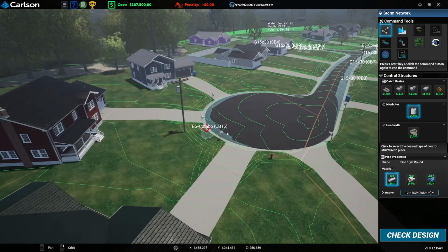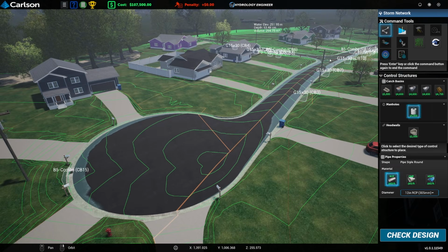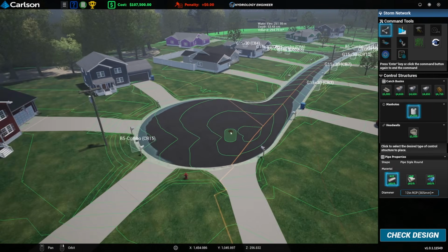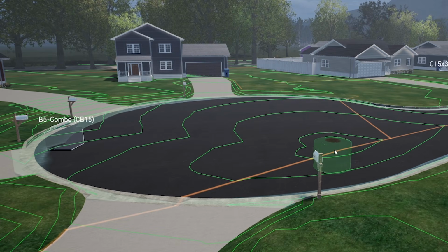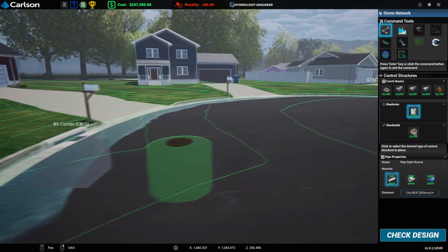We've got our gully up this way. We can see the road flows downhill over there, so that's quite nice. The thing I don't like is the high point is actually there. So whatever we do over this way, the pipe coming out of there is going to be flowing against the gradient of the road, which means it's going to be getting deeper and deeper, which isn't great.